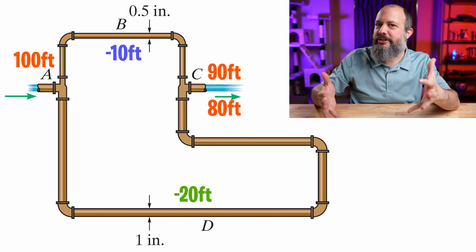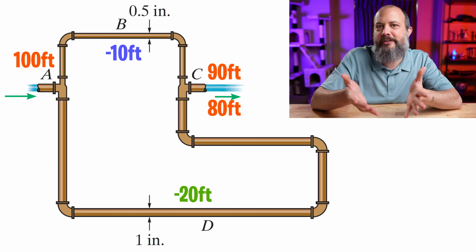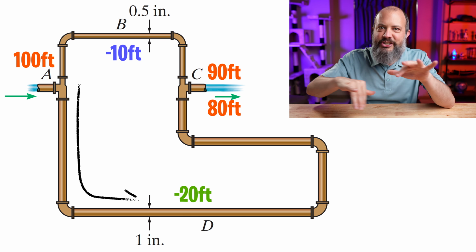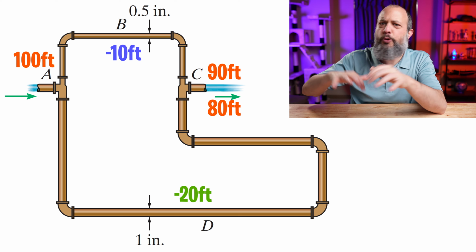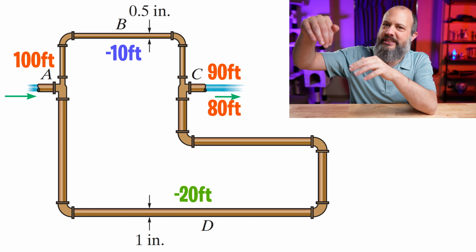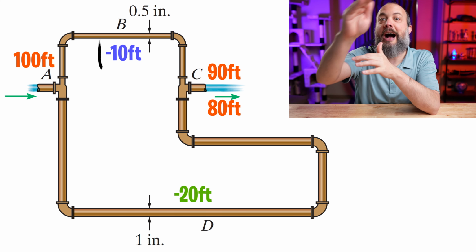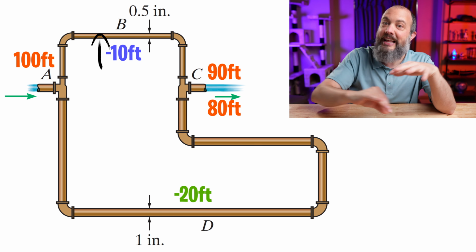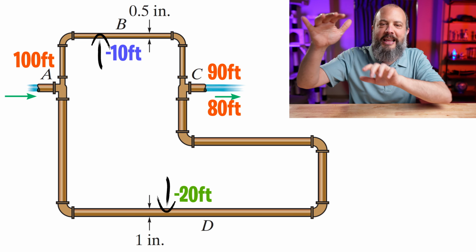The way that this happens is that fluid will change how much goes through either path in order to equalize the head loss. Imagine in this scenario, again, where there's 10 feet of head loss up top and 20 on the bottom. If there's so much extra friction at the bottom that it would create so much extra head loss, the system would equalize itself by having some of the flow, instead of continuing downward, divert upwards. By pushing more flow upwards, it would be going at a higher velocity and have higher head loss. And the bottom path, since it has less fluid flowing through it, might have less velocity and less head loss. So the amount of flow will fluctuate in order to balance the amount of head loss in every path.